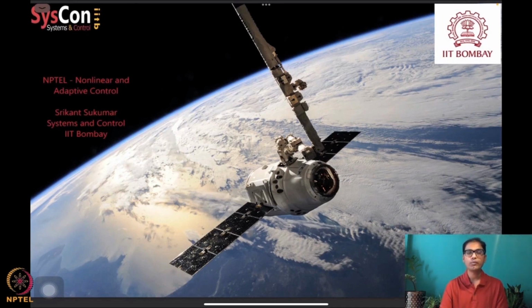What we can actually show is the construction of the complete candidate Lyapunov function for the system when an integrator layer is added to this. We can also show that our backstepping error goes to 0, and that whatever your w is, that is, the negative semi-definite function we had from the first integrator layer, will also go to 0. This is what we have been able to show until today, and in the subsequent lecture we will look at what is called the extended matching design.